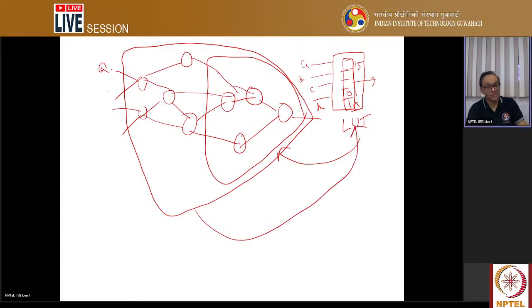Now the question here is how do you identify what is the biggest one, right? If you start from this node and try to do a DFS kind of thing, whenever you get 4 inputs you stop and say I'll put this into a LUT. Then that is suboptimal, right? So what I have seen here, the design I have taken, I can map the entire design itself into a single LUT, right? So this is how the tool works, right?